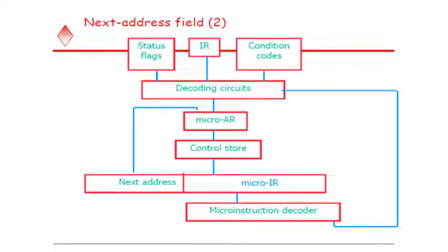The microprogram shown in the previous figure requires several branch microinstructions. These microinstructions perform no useful operation in the data path. They are needed only to determine the address of the next microinstruction. Thus, they detract from the operating speed of the microcomputer. The situation can become significantly worse when other microroutines are considered.